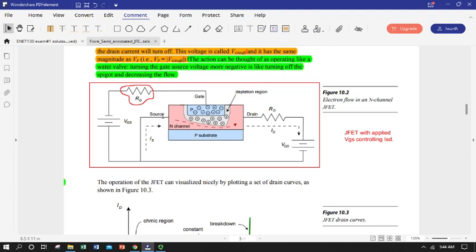Generally speaking, there is less difference in source to drain characteristics in the device than necessarily collector to emitter. They are not necessarily interchangeable, so please don't hook them up backwards. They won't work as well. But the big difference is gate to source or gate to drain. Our current is going to flow source to drain.